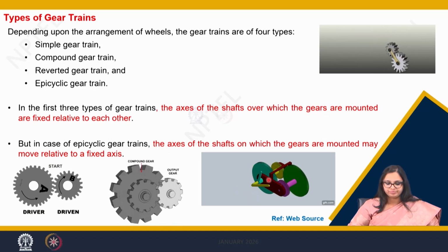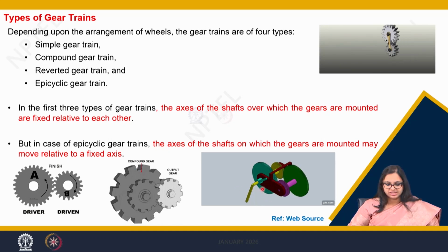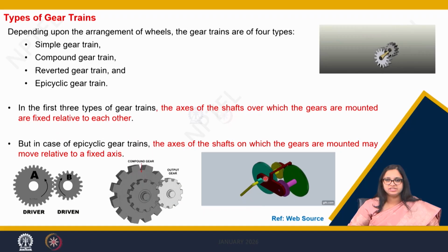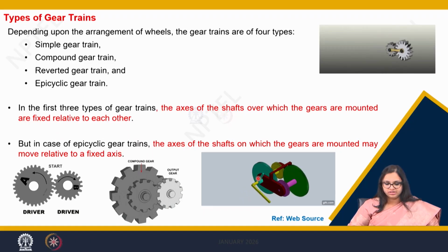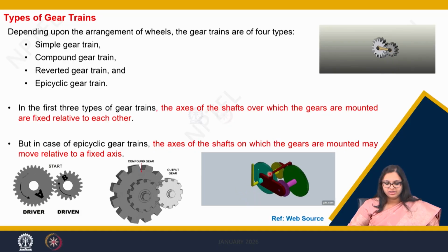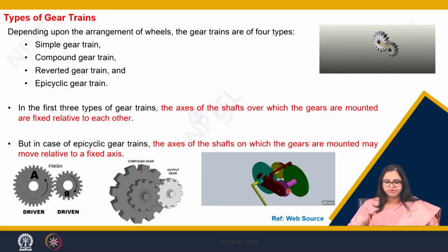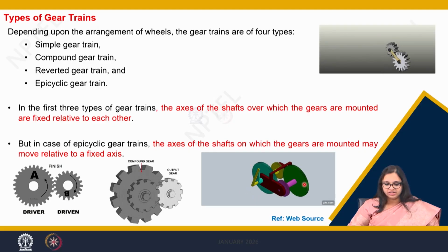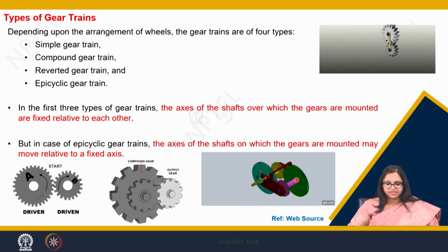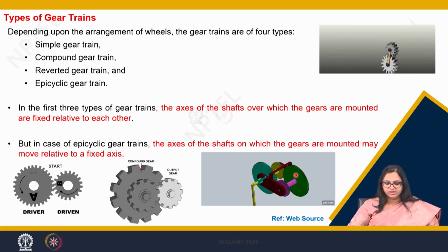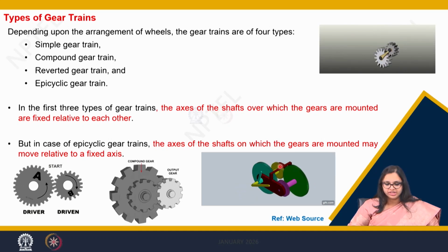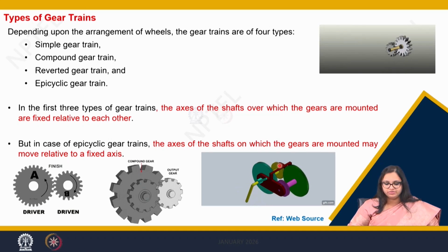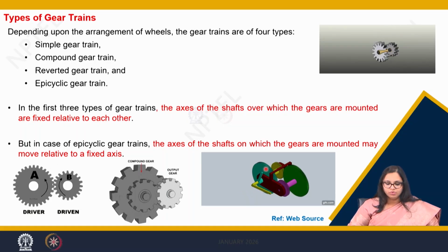There is no joint in between these two gears. You can see here, let's say this green one is moving at a certain velocity, which you can see with this lever that is attached to this gear moving slowly. Now this is in mesh with this purple one. Now the purple one and this dark green one are housed over another shaft, which is in pink color. Now this green gear is in mesh with the yellow gear. Now you can see the speed of this yellow gear is more than the speed of this green one.